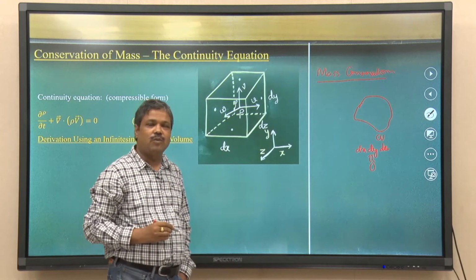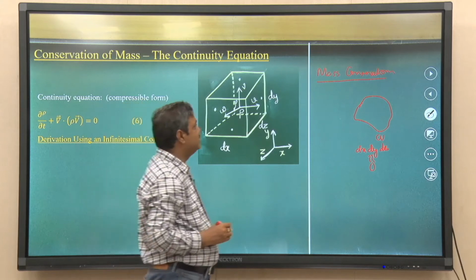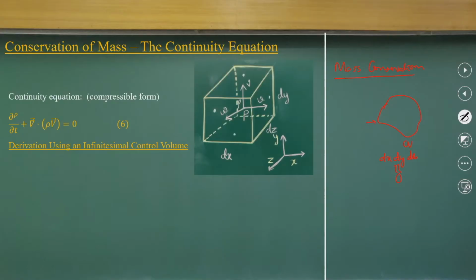So, when you have the control volumes infinitely small, in that case we are looking at how we can have a differential equation format for the mass conservation equation. As we derive it, the basic components are: rho is a density field, which is a scalar quantity, a function of positions x, y, z in Cartesian coordinates.